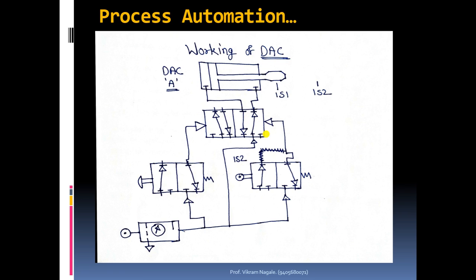Because of this, the linings inside this left side block will now take control of the air on the output side as well as on the input side. That means it will transfer the air which is given to port 1 to the output side at port 4.